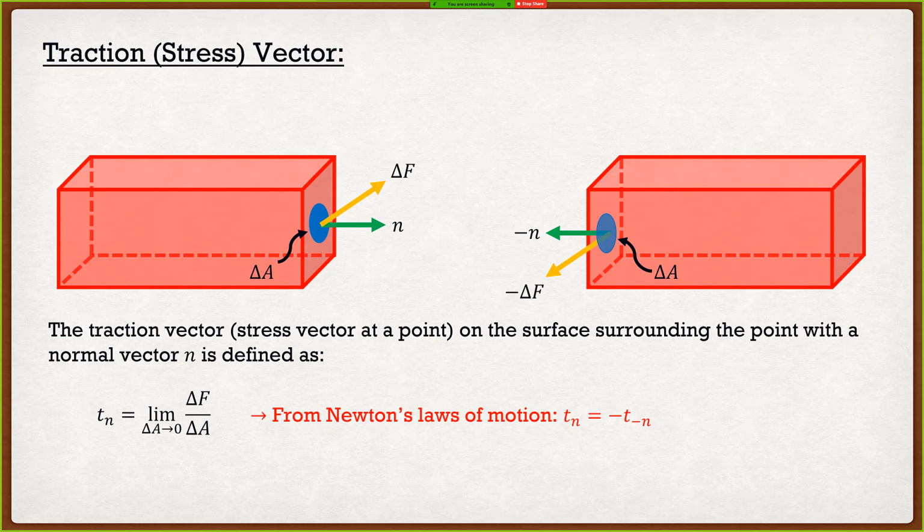Now, you guys may be wondering, traction vectors, what basically is this? Well, I just want you to think of traction vectors like this, because that's the formal definition, and no one likes the formal definition. Basically this: if I were to take a beam in statics and chop it up, I have my shear, I have my normal force, and I have my bending moment. What we're dealing with now in these 3D objects is that when I cut my beam, I basically have a vector of stress components. So when I cut something, I now have stress components.